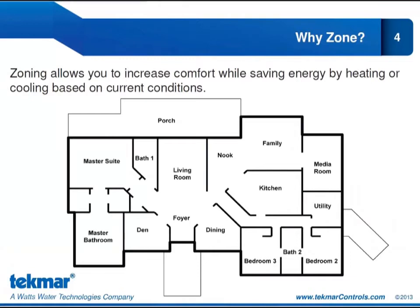So zoning gives us that ability to save energy by delivering heat only where we need it, in the amounts we need it, and not to put heat in rooms that potentially have low occupancy, or because of the solar or equipment gains in that room have lower heat needs than the other zones within the space. Zoning is really easy to do with hydronics, and we will design the hydronic distribution system based on the individual needs of the zones.